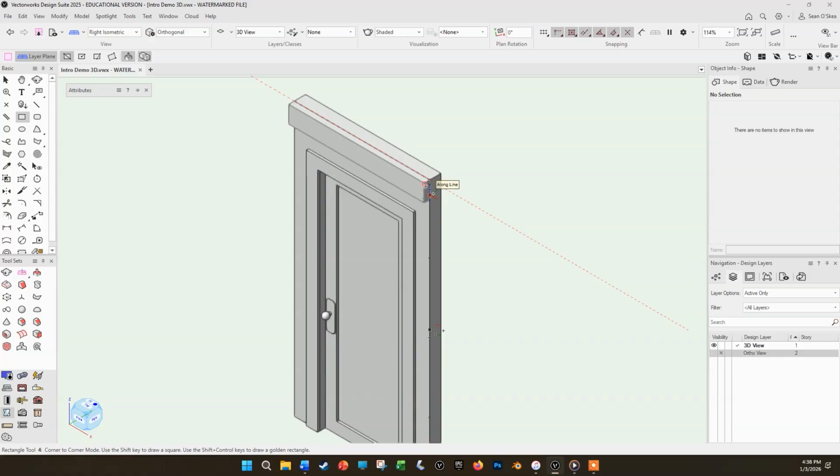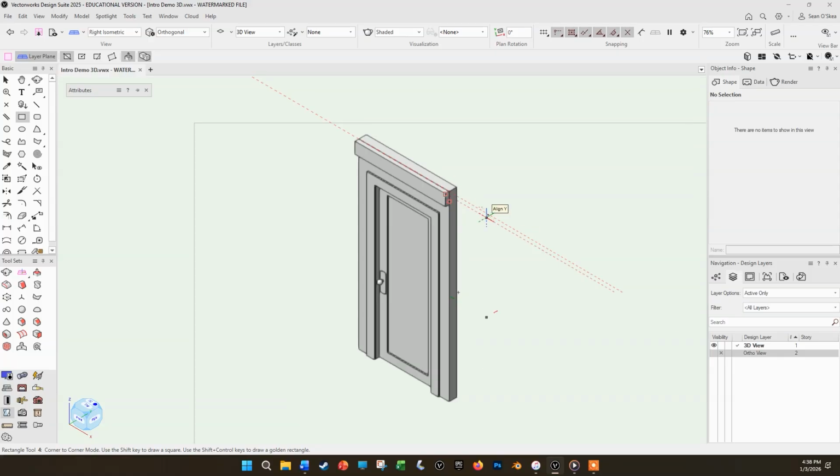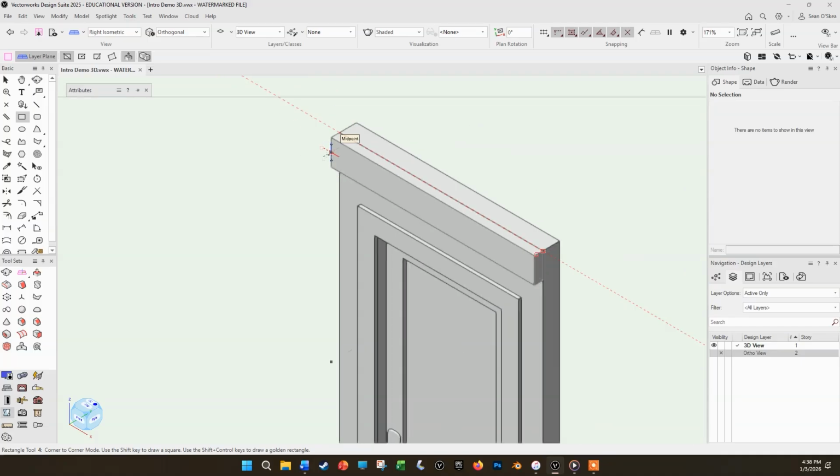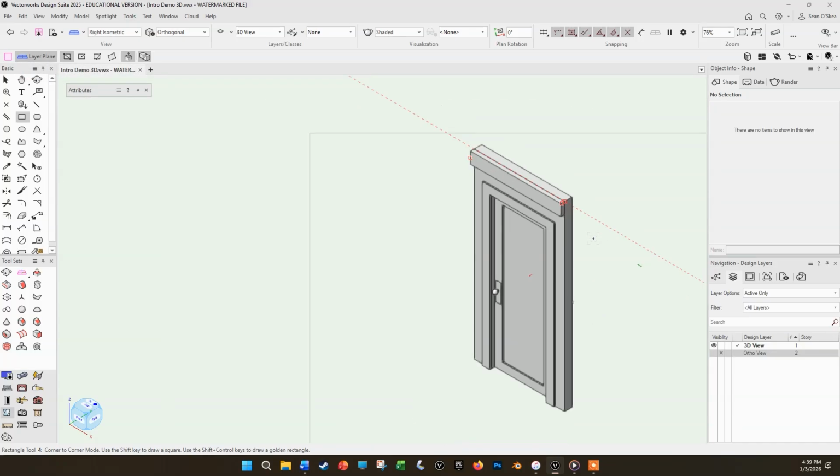And remember from the add and clip surface video how easy it was to draw a square on, then draw a circle on top, and use clip surface to create the cove molding profile. And you can always draw on the layer plane as we've been doing, and then extrude the shape and then rotate it into place. But there's a much faster way. We can draw the profile right into the spot where we want it by using the automatic mode or the auto plane mode. So far, we've been drawing in top plan and then extruding things up in the Z direction.